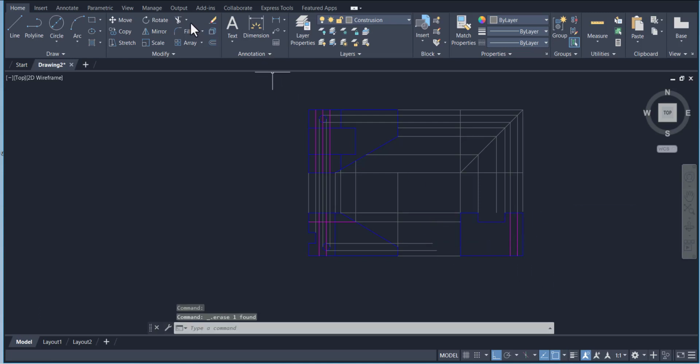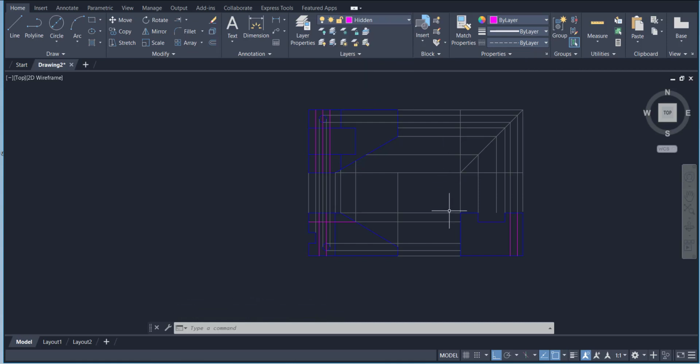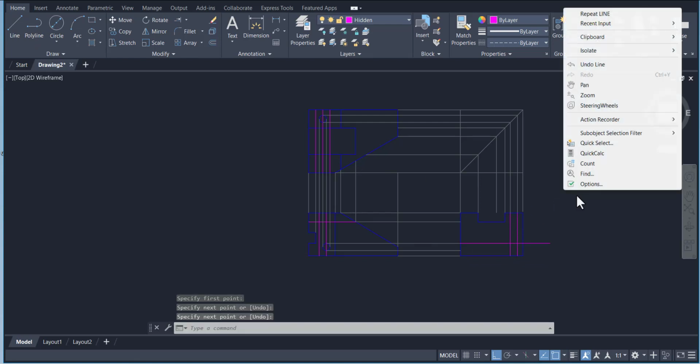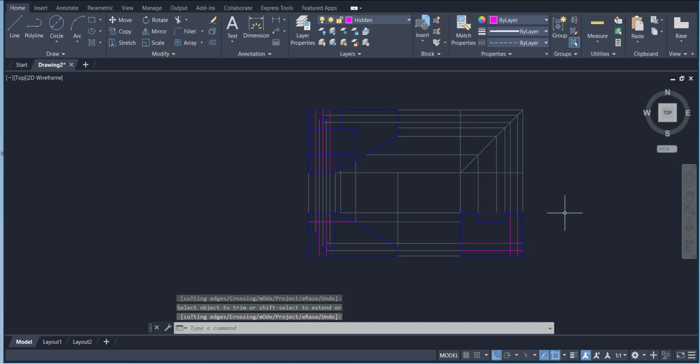So for explanation, I am doing that, and it also looks like a good method if you draw like that. And then go to hidden lines, because these 2 points are for this circle. We are transferring it to the right side view, and it will be hidden on this right side view. So we just draw like that and like that, and then just trim this over.